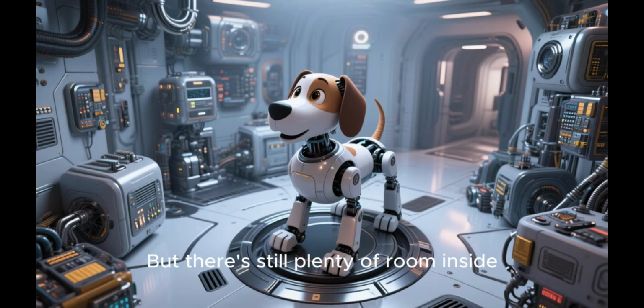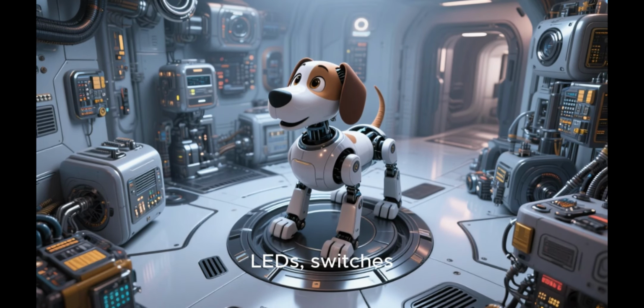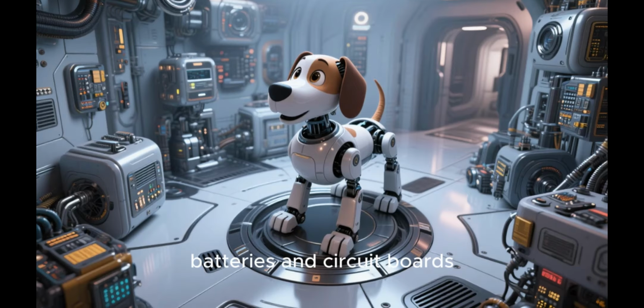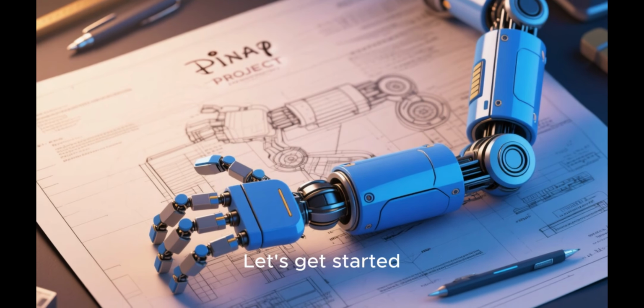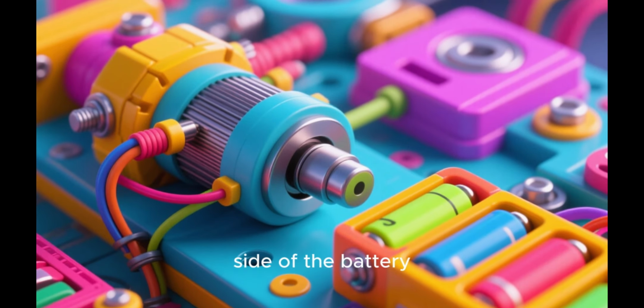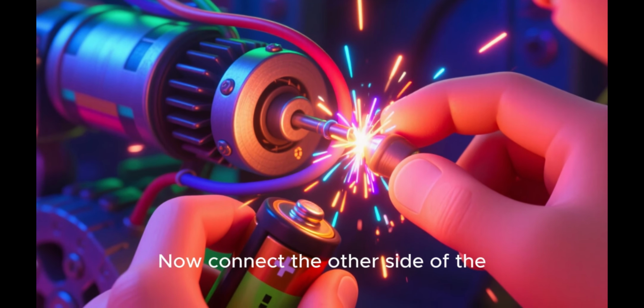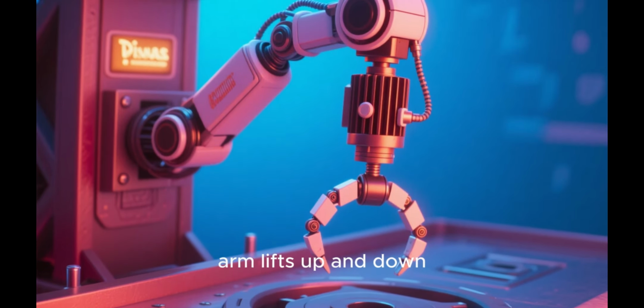Neat trick. But there's still plenty of room inside the robot dog for more motors, LEDs, switches, batteries, and circuit boards. What else can we make? How about a robot arm? Let's get started. Connect one side of the motor to the positive side of the battery. Now connect the other side of the motor to the negative side of the battery. Turn on the switch and the arm lifts up and down.